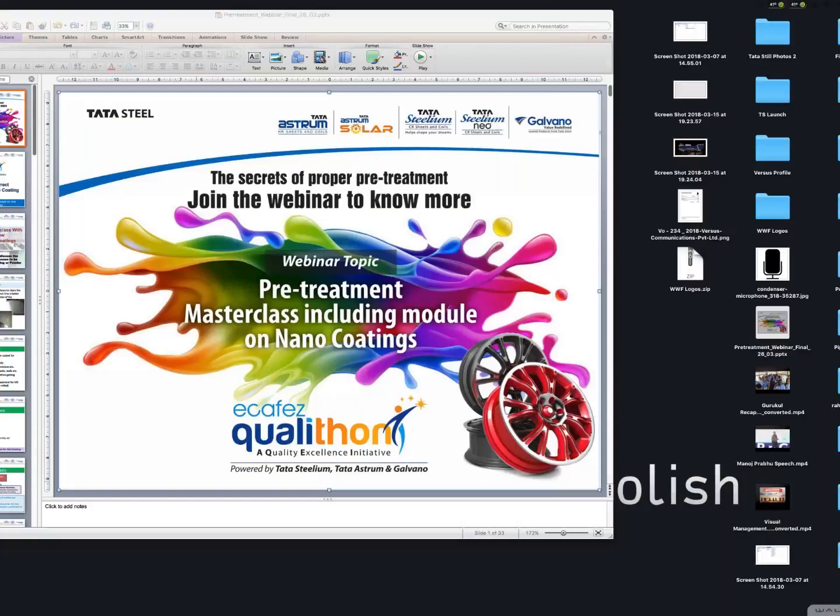All chemical suppliers say 120 degrees for WDO, not more than that after PT. Our processes depend on powder curing temperature like 180 degrees for 10 minutes. In that case, is there any effect on the PT layer? No, I don't think after you coat with powder there is any effect on the PT layer. Otherwise, it would not have been recommended for powder coating at all.